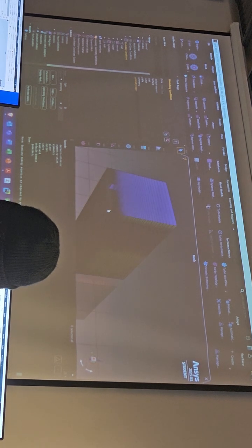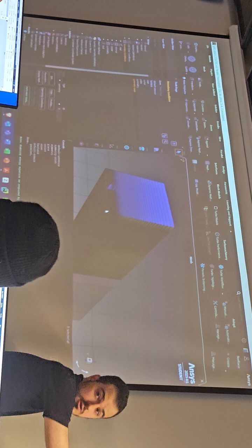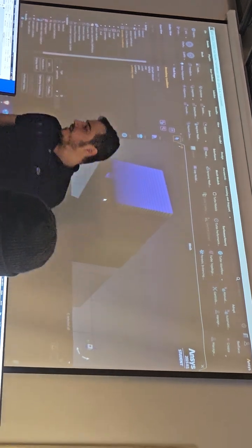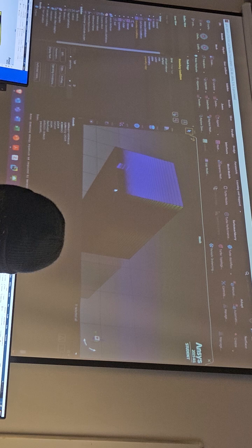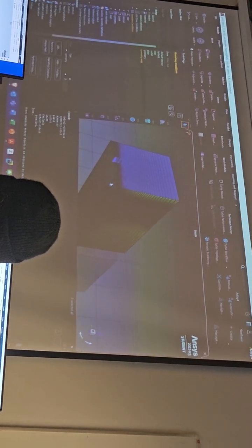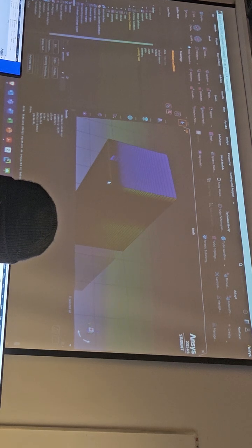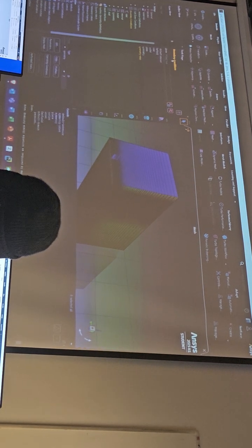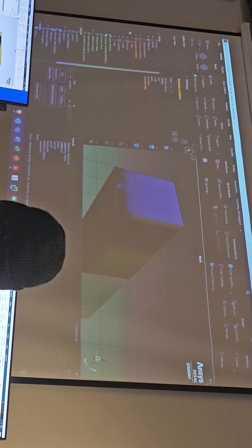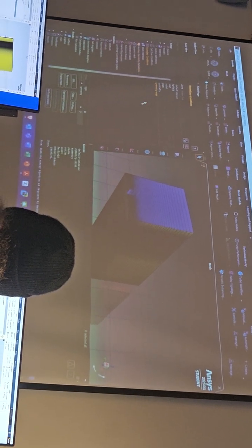And then finally, symmetry inlet, that is that small surface at the beginning of the domain. Last week we set it like a slip wall, because for the mixing length model, if we set it like a symmetry, it was having some issues. But this time, with this turbulence model, we can leave it like a symmetry, and it's going to work fine. So we don't need to change that.